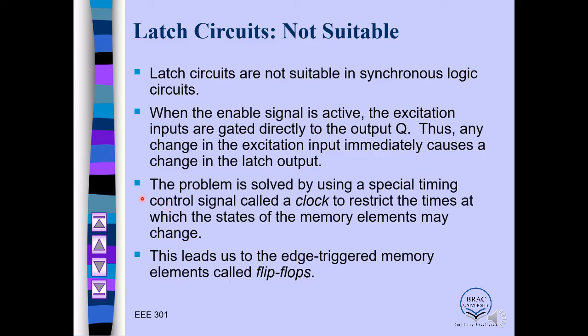The problem is solved by using a special timing control signal called a clock. So, using a clock, we can eliminate this kind of situation and restrict the times at which the state of memory elements may change. This leads us to the edge-triggered memory elements called flip-flops. So in a flip-flop, this kind of problem is actually solved.